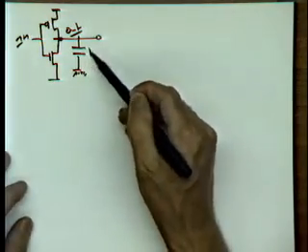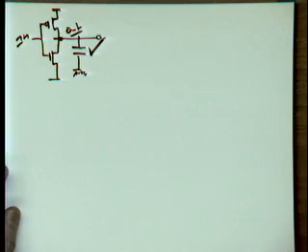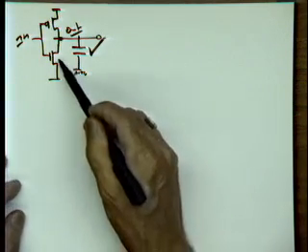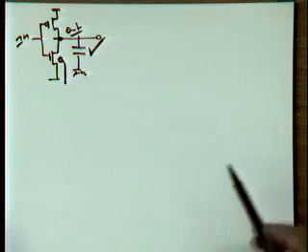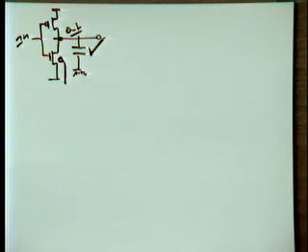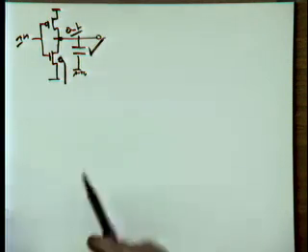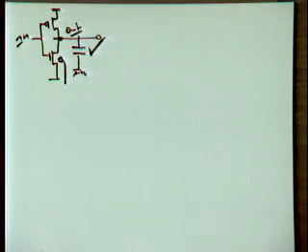So what I said already is, I linearized the capacitance and I lumped it. The transistors, however, are also nonlinear elements. Right? They go to different operation modes. And as a result of that, the current characteristic can change as a function of Vin. So these are all nonlinear. So what we're typically going to try to do is replace this by a linear element.